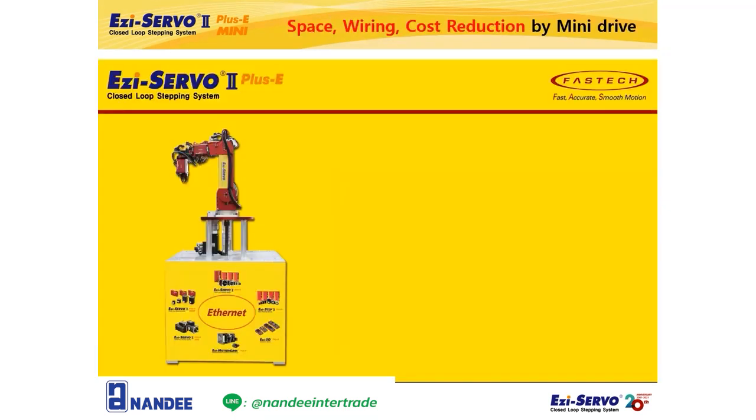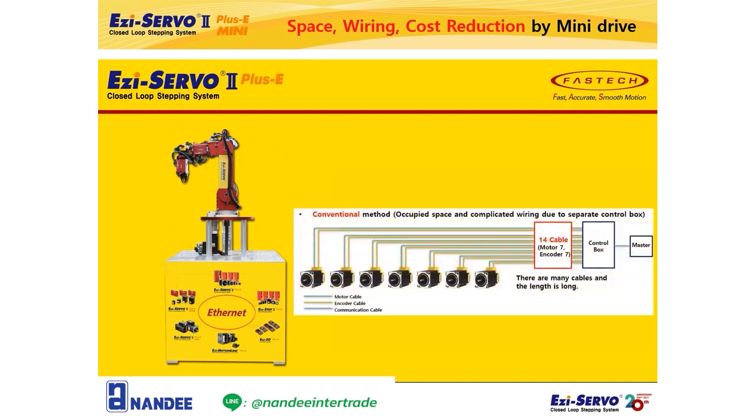First, to explain space savings, wiring savings, and cost reduction, I will show you a 7-axis robot as an example. In general, to operate 7 motors installed on a robot, 7 motor cables and 7 encoder cables are needed. There were a lot of wires because a total of 14 cables had to be connected to the drive installed in the control box. In addition, a separate control box for the drive was required, taking up space.